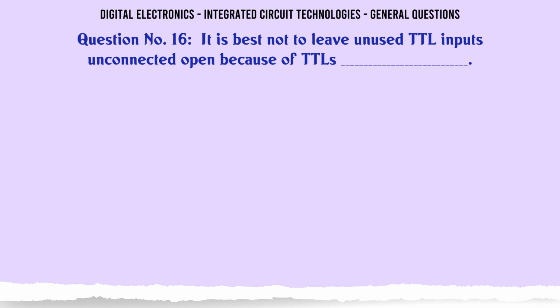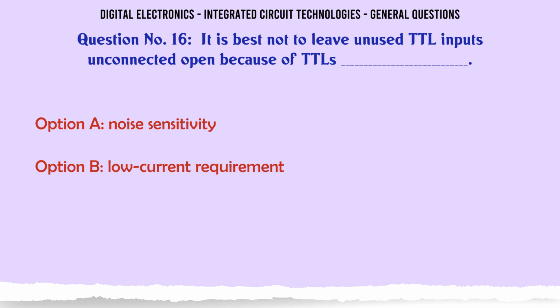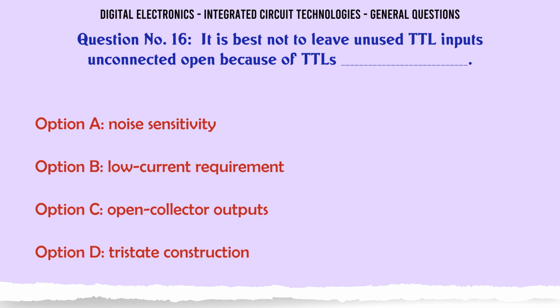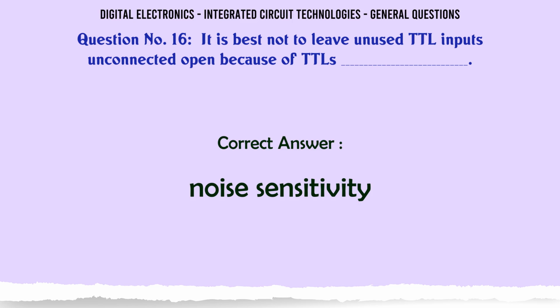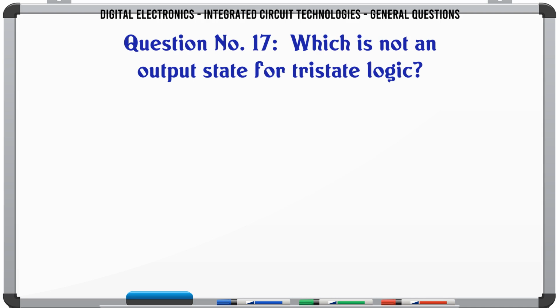It is best not to leave unused TTL inputs unconnected, open, because of TTL's A, noise sensitivity. B, low current requirement. C, open collector outputs. D, tristate construction. The correct answer is noise sensitivity.